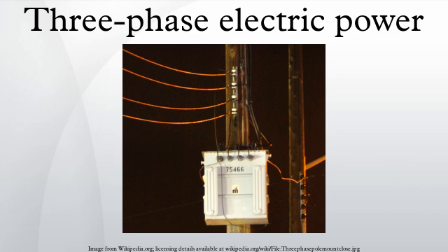In such a device, the energy storage is performed by the inertia of the rotating components. An external flywheel is sometimes found on one or both ends of the shaft. A 3-phase generator can be driven by a single-phase motor. This motor-generator combination can provide a frequency changer function as well as phase conversion, but requires 2 machines with all